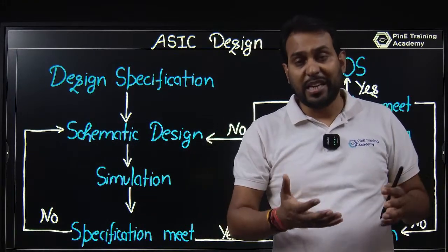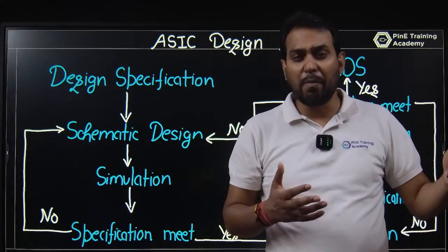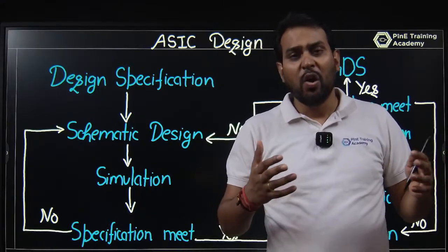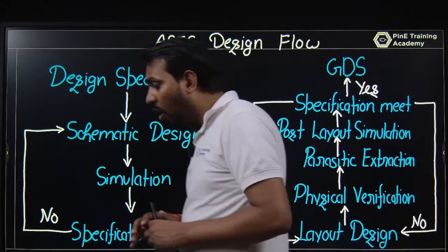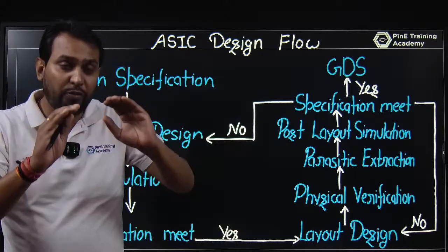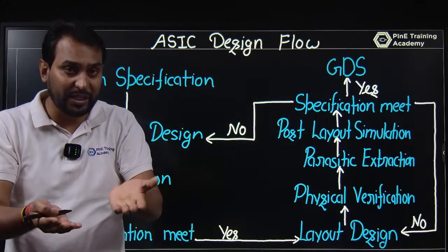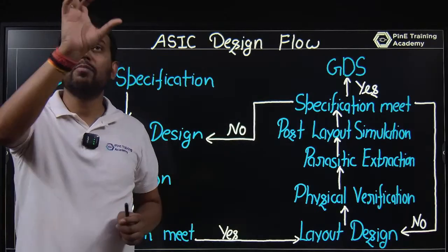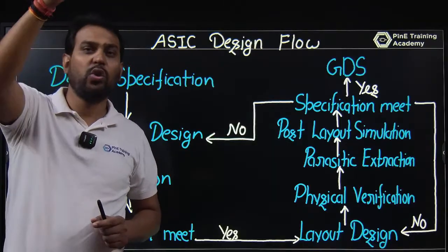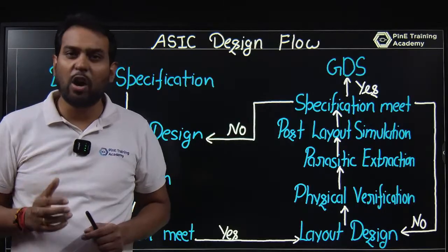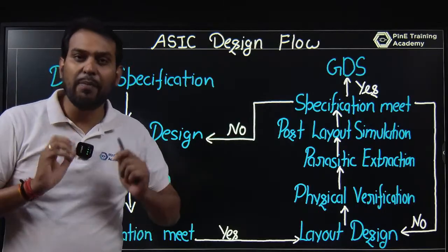It's layers, that is base layers: N well, P implant, N implant, OD. Okay, a lot of things are here. So for that layout, just think of it as the conversion of a schematic to a pictorial representation. You have a CMOS inverter, a PMOS and an NMOS, the input is connected, you have VDD, you have VSS, and you are taking the output. So this is a schematic.